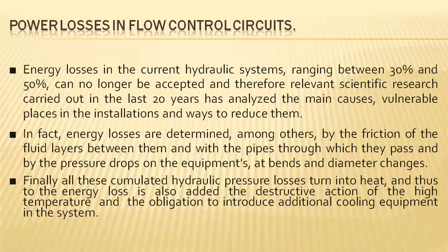Power losses will be considered. If these power losses or pressure drops are considered, obviously the pressure at the end actuator, which needs to be operated at 5 bar, will decrease. For example, if 1 bar of pressure is dropped due to these power losses, then instead of generating 5 bar at the actuator, only 4 bar will be circulated. This 4 bar will not be sufficient for driving that particular actuator in a prescribed timely basis.